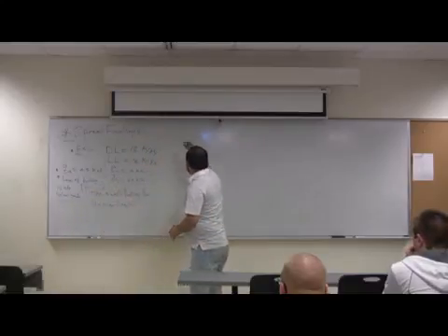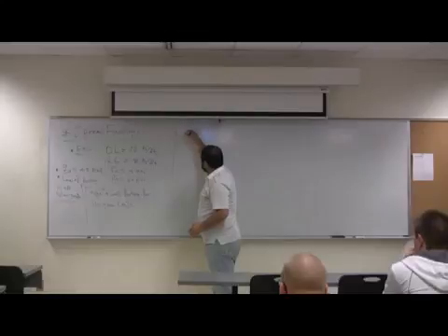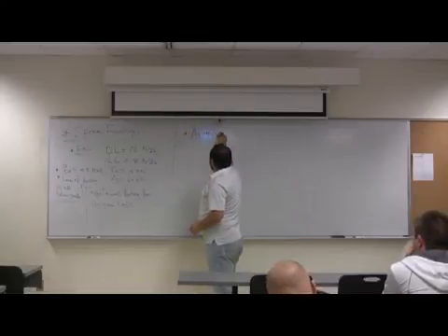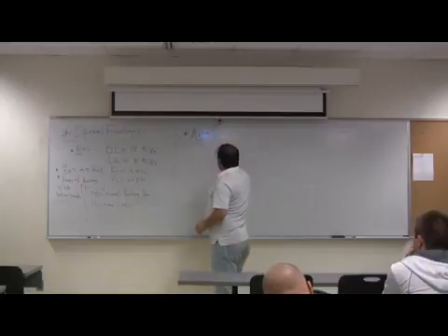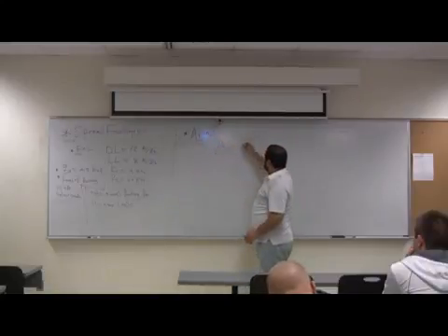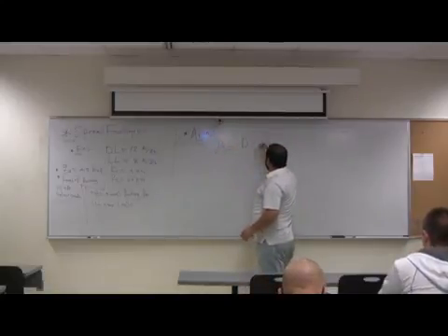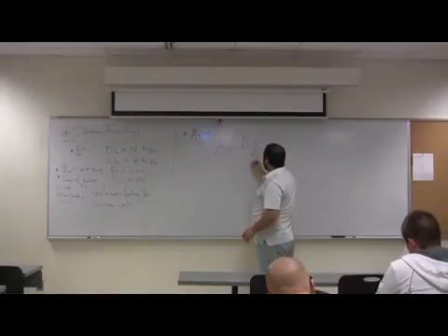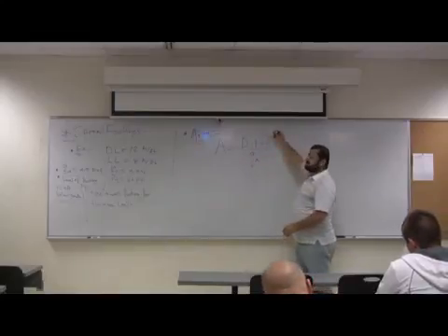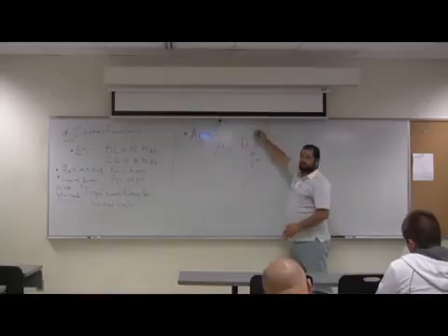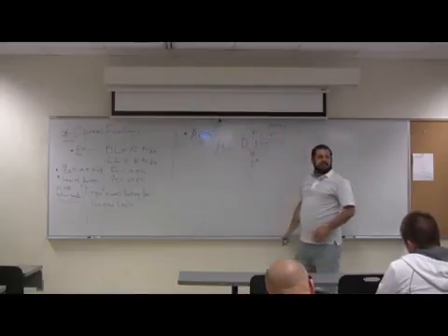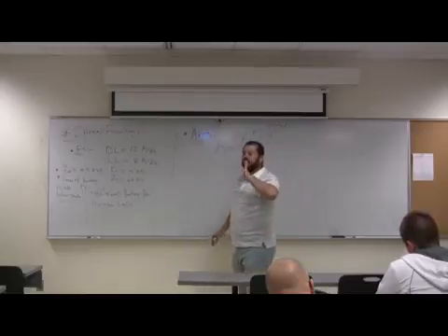So the area, the first thing you calculate is area. A equal D plus L divided by Q allowable. You see these loads here? Service loads for calculating the area.